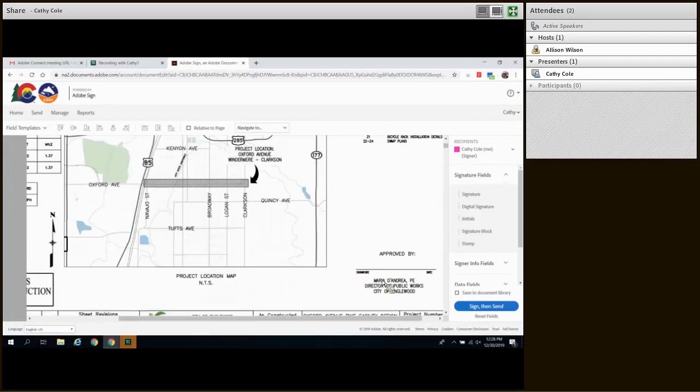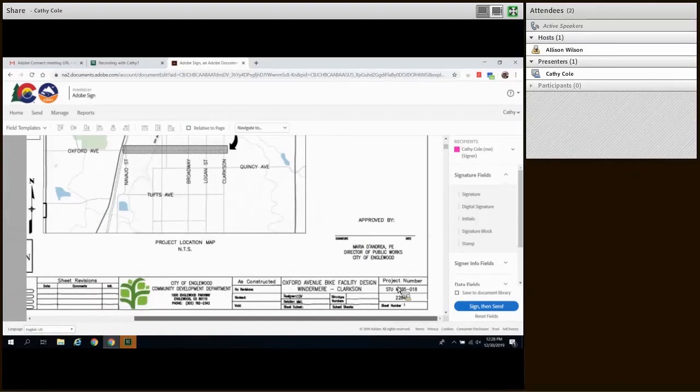We try to seal record sets in the lower right-hand corner because we want this to be consistent, whether it's one engineer or 20 engineers signing. We want the size of the seals to meet AES board rules, which is 1.5 inches square or 1.625 inches. We also need to limit the scope of the authority of that which we are sealing, whether it's for bridge work, road design, or whatever it is. So templates have been created to minimize the work so that the size and the location is consistent. Current AES rules require each and every sheet of a plan set to be sealed.